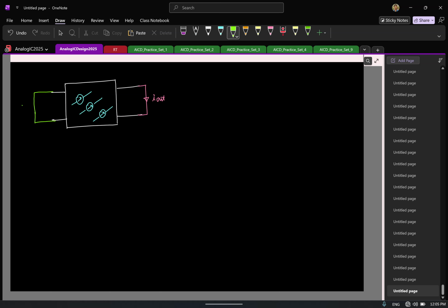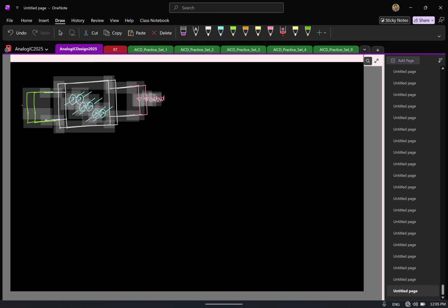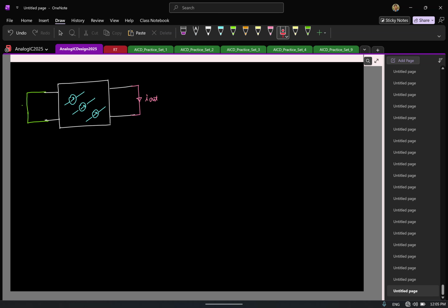And then I have so many noise current sources. So you can again use superposition. You take one noise current source at a time. Let us say I'll consider the kth noise current source having a power spectral density of S_ik(f).